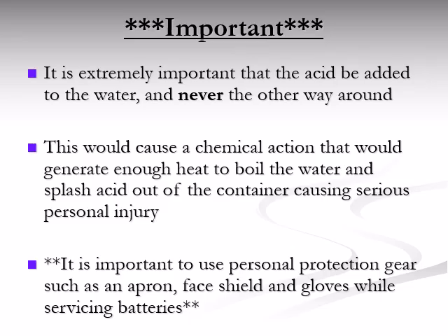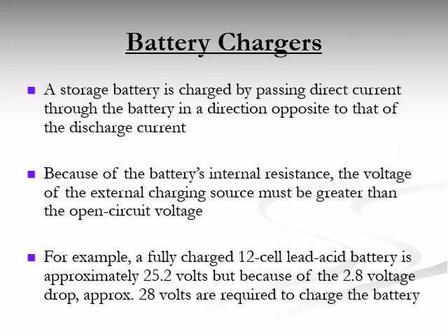Note the following important safety tips. Always add acid to water, not the reverse. Wear protective gear to prevent burns or splashes from battery acid. Charge the battery by applying DC opposite to discharge current. The charger voltage must be higher than battery voltage to overcome internal resistance.